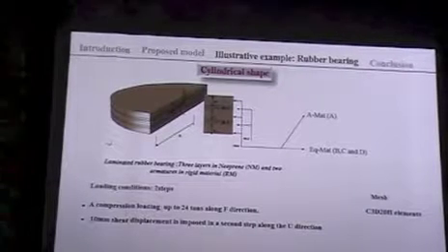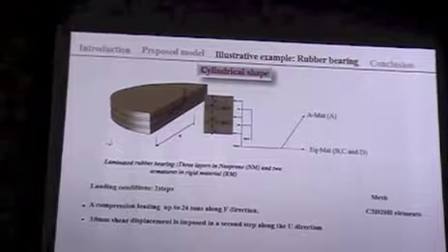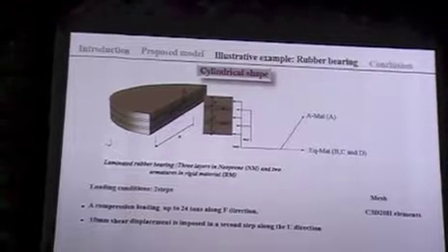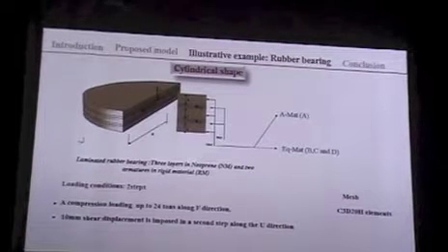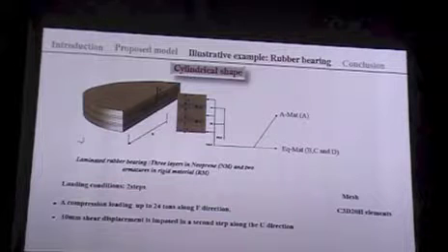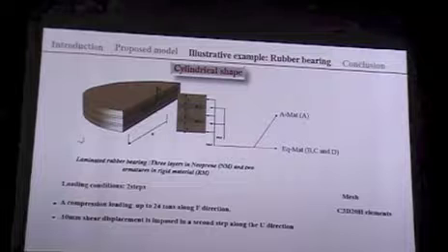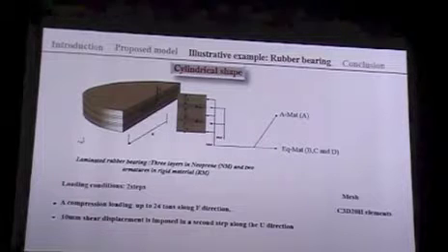To reach different compressibility and different Mooney material parameters, even with the same concentration of ingredients, we change the curing time and temperature, and we get different compressibility moduli for the same neoprene material. We try to control the length between the macromolecular knots, and so we have different compressibility moduli.